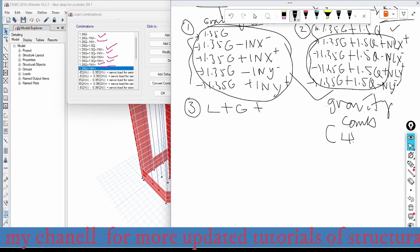That means excluding what? Live load reduction factor is not considered in the case of gravity load combinations. And in the case of seismic load combination, we will consider this live load reduction factor. So how to do this one? Simply, in the case of seismic load combination, we will not use this factor. That is 1.35 and 1.5 combination factor will not be used in the case of seismic combination. So the first load combination for seismic is the case of seismic.